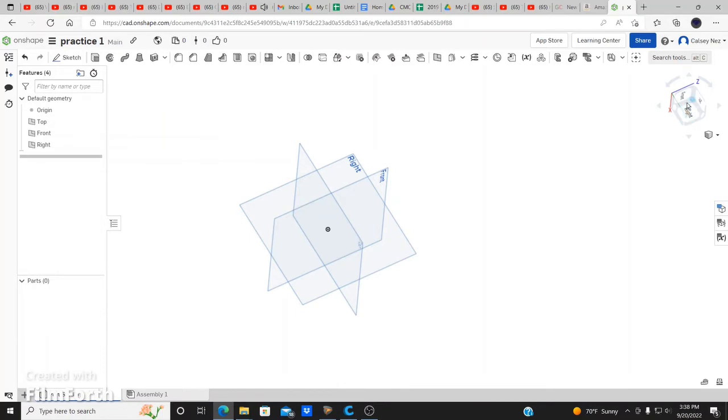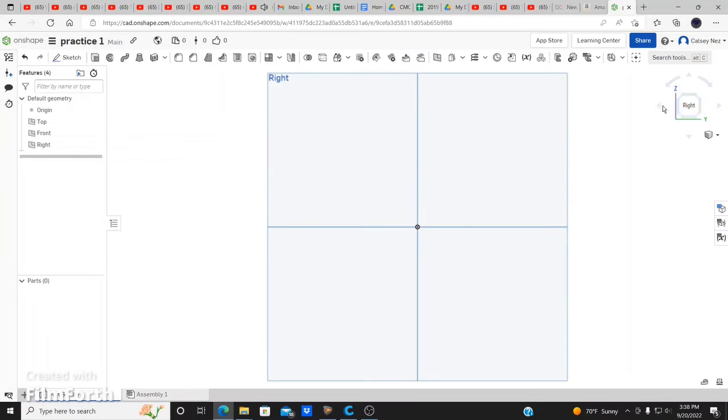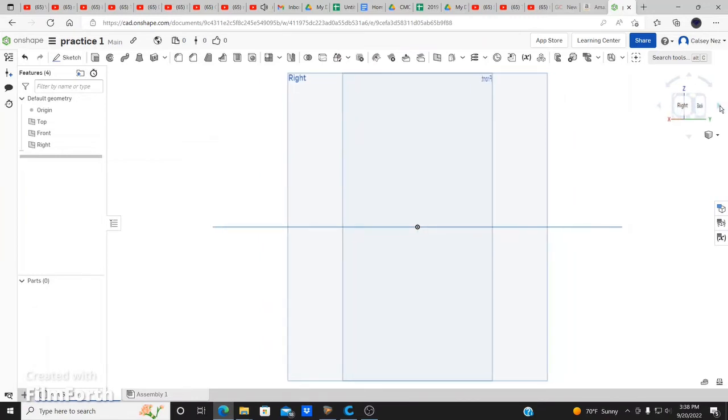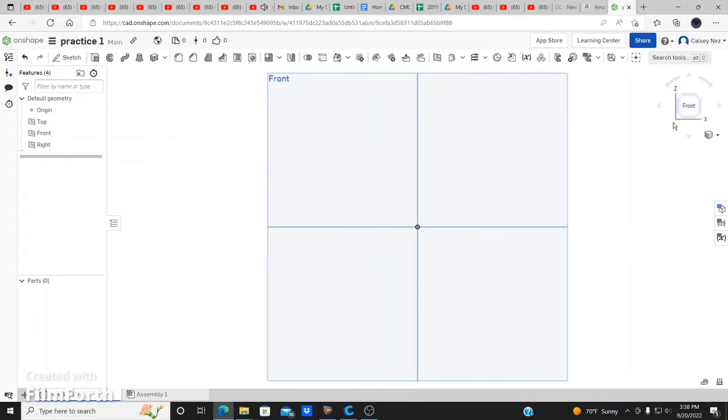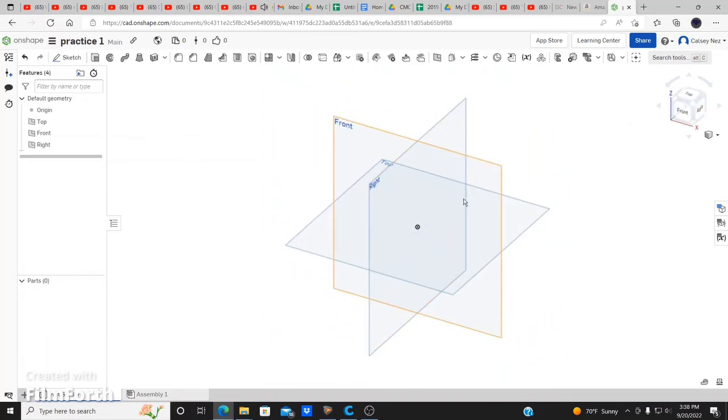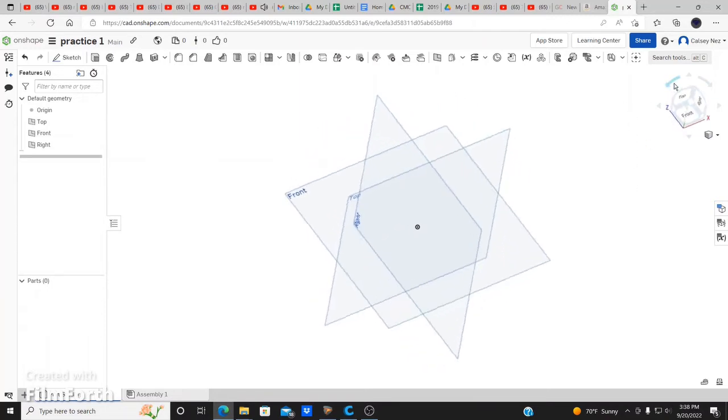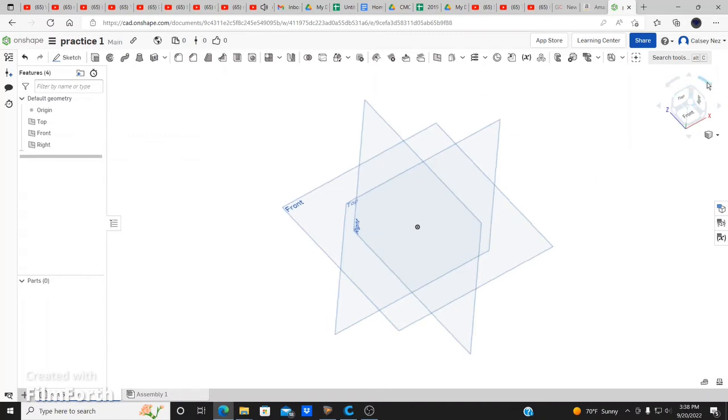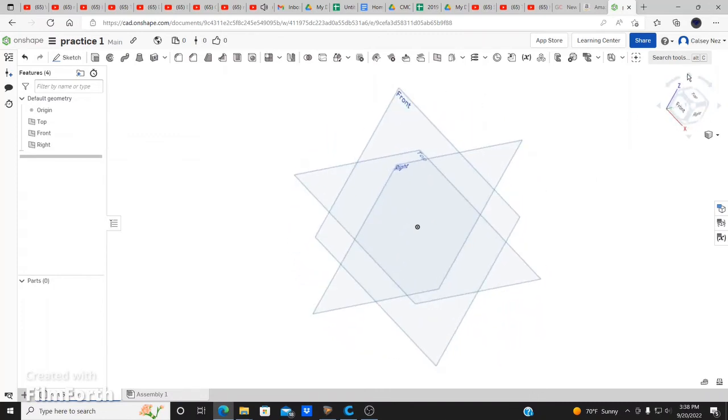You just select the specific areas that you want, like the right view, and it'll rotate to the right. There are these little arrows, so you can rotate it just slightly. You can see the back and front. You can select the front, either way. You can select the corners, like the top one, and it'll give you this isometric view. If you want to rotate it, you just select this way. You can rotate in that direction, rotate this way, tilt it back, and this is how it works with the cube function.